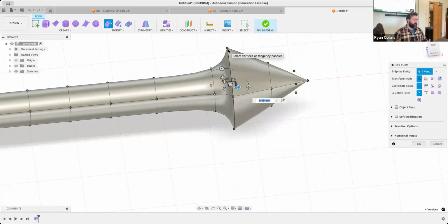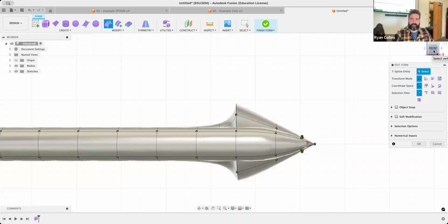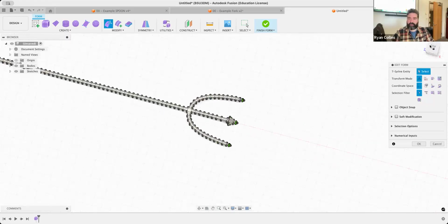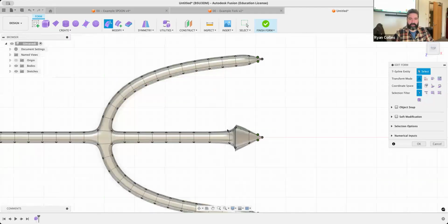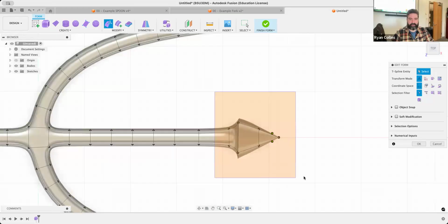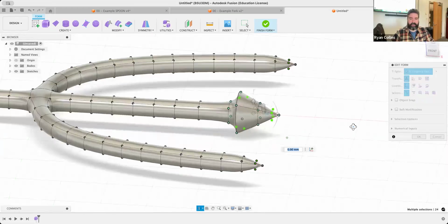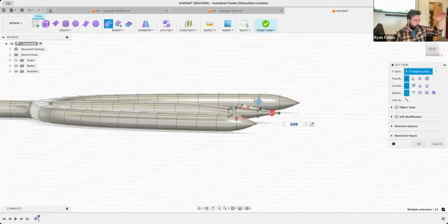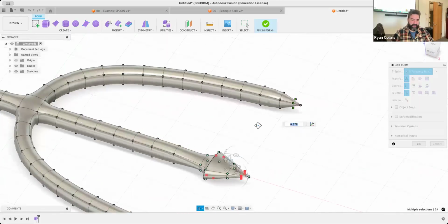So like when we're working with fit point splines, if you make them too far apart, you get a nice smooth curve. But if you wanted a sharp point, you either needed to start and stop a point or drag them or make your points much closer together. And this is just the same thing. If I was trying to flatten this, maybe I'd take the whole thing. Ooh, way too many. So maybe I would take all of these by vertex and then orbit over and use a scale and shrink it in one direction. And now it's a bit flatter.